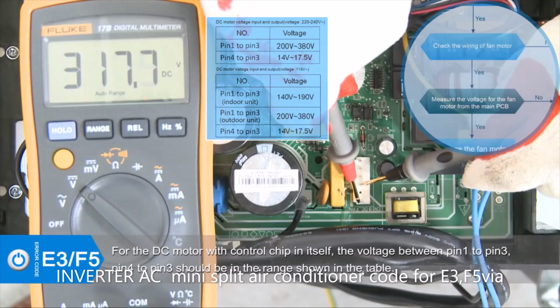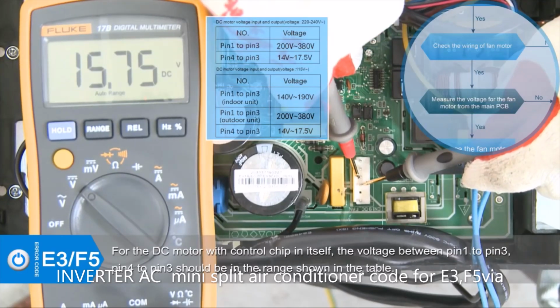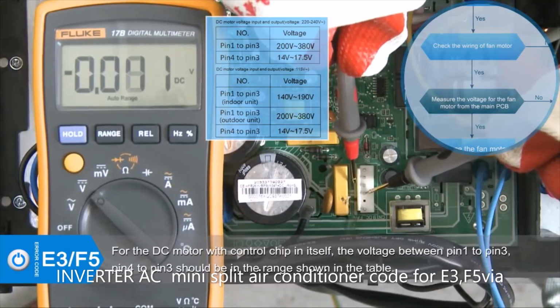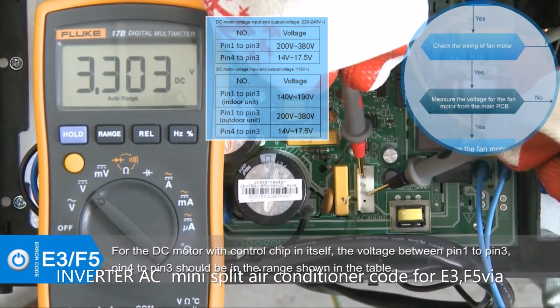Examination for main PCB board. DC motor with control chip in itself. Turn the power on. When the unit is in standby mode, measure the voltage between pin 1 to pin 3, pin 4 to pin 3 in fan motor connector. If the value of the voltage is not within the range shown in the table.